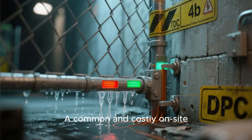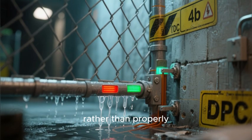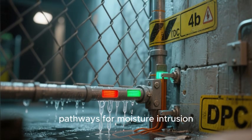A common and costly on-site mistake is when bricklayers cut the DPC to fit around obstacles rather than properly detailing these transitions, creating permanent pathways for moisture intrusion.